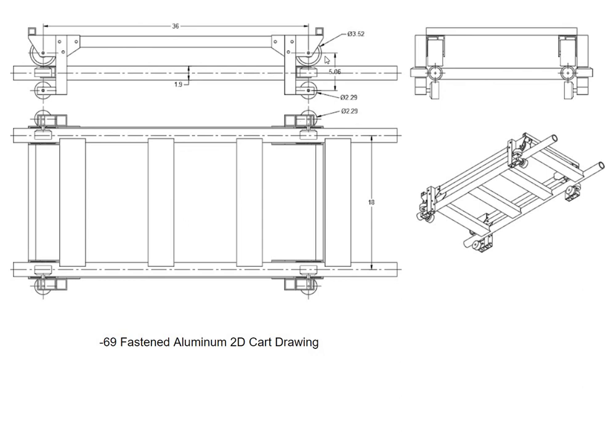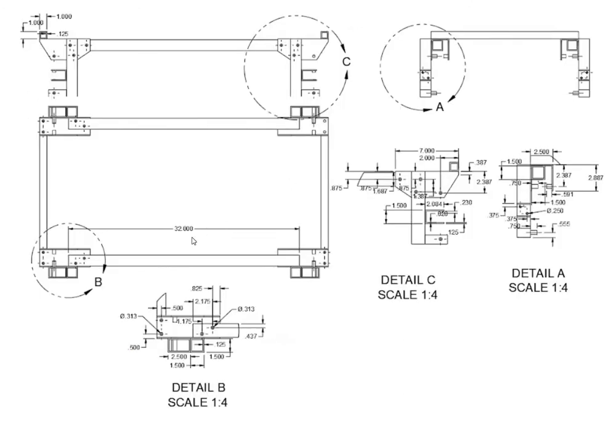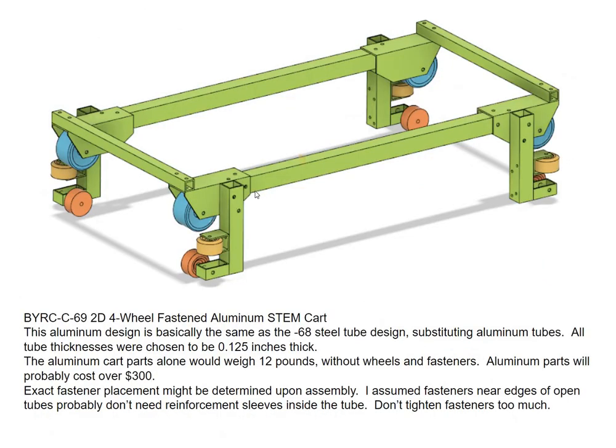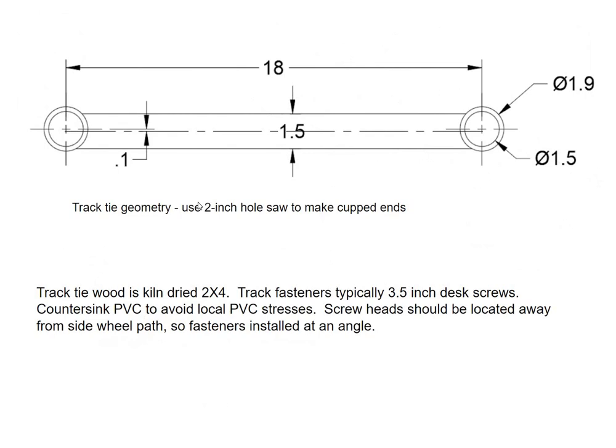It's got 70 millimeter wheels and 52 millimeter roller skate wheels for the side wheels and up stops. And here's some more details. You could stop this and look at it if you're really interested in doing this. It's not that great of a drawing, but basically, I would give you this model in a STEP file. There's a couple of different model file formats that I can send this to, and you get it and read it in and just work from the model. Don't work from the drawings. That's how modern people do it.